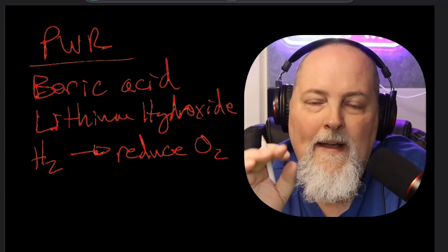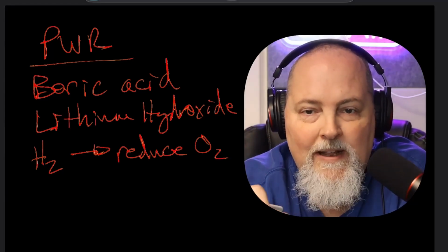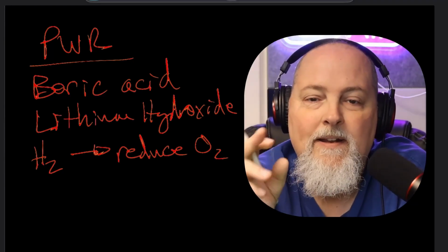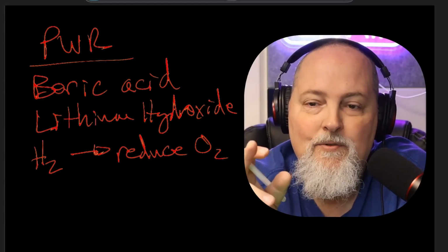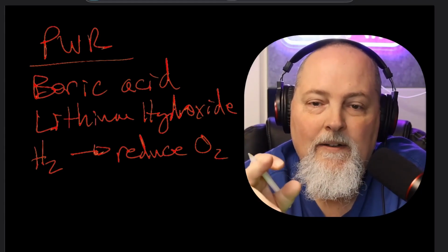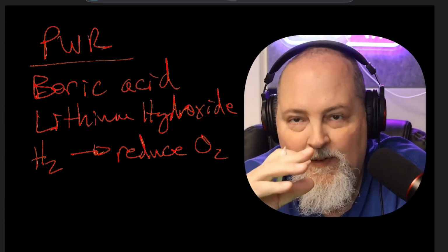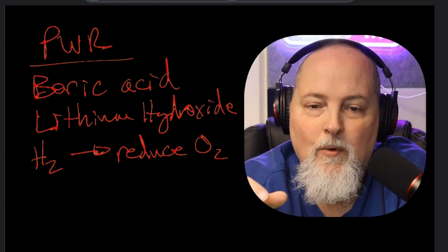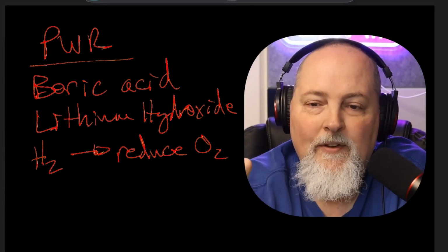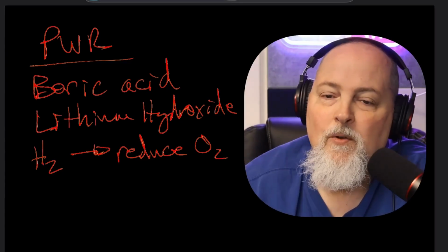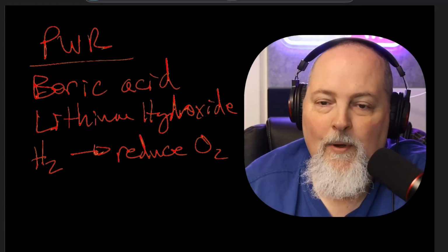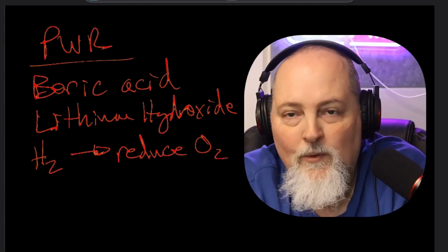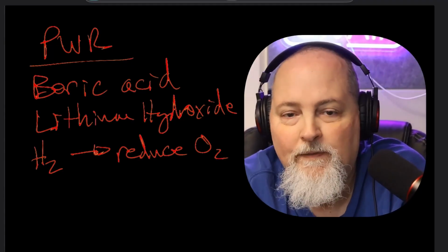But if hydrogen's depleted and oxygen stays, oxygen and nitrogen form nitric oxide and nitric acid. The nitric acid drives the coolant acidic, and that's a bad direction. We would prefer to have it slightly basic than slightly acidic. The low pH increases corrosion and can destabilize the protective oxide films. We do feed and bleed to help reduce that concentration, and like on submarines, we would add ammonia to help shift that.